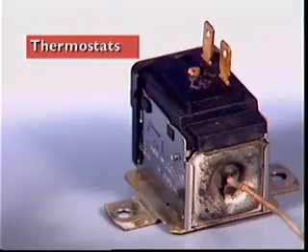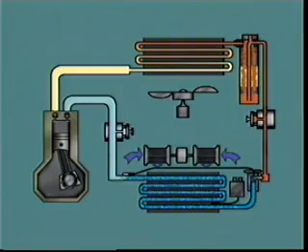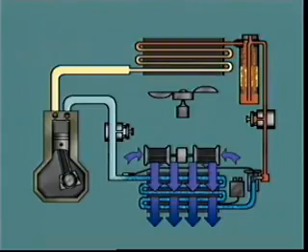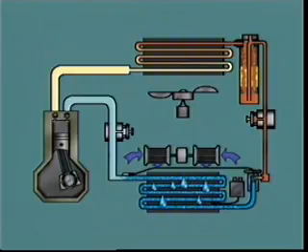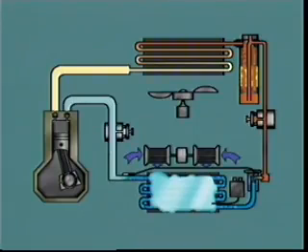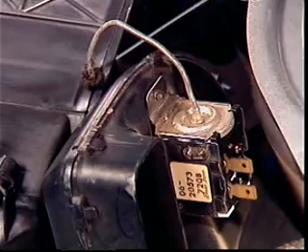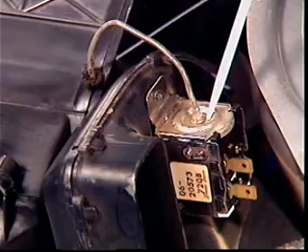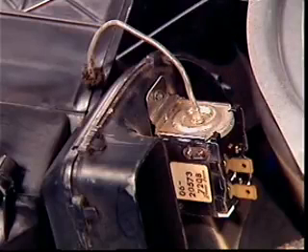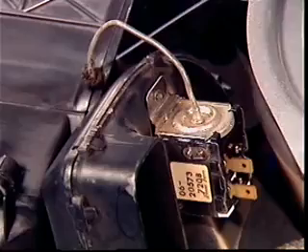This section examines thermostats. When warm air passes across the evaporator fins, the cooling action causes water vapor in the air to condense and adhere to the fins in the form of water droplets. If the temperature of the fins drops to 0 degrees Celsius or below, ice will form on the fins, restrict the airflow, and prevent heat being transferred to the refrigerant. A thermostat is used to monitor the temperature of the evaporator fins and control system operation within set limits.